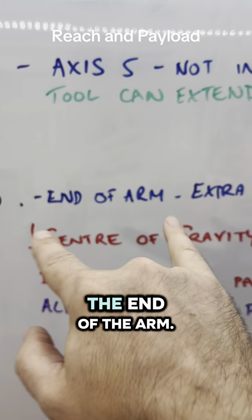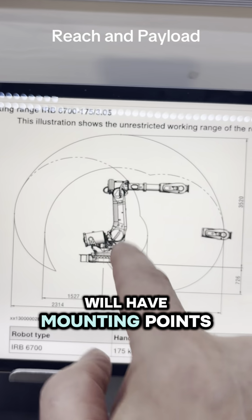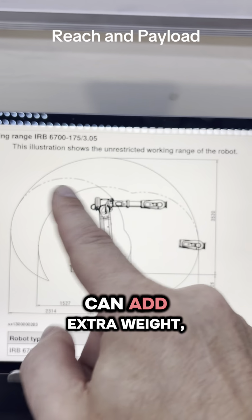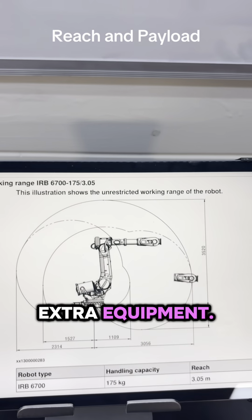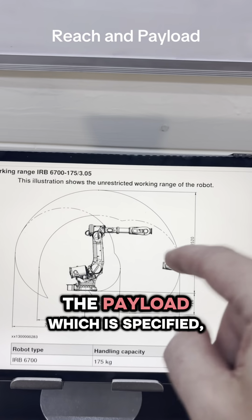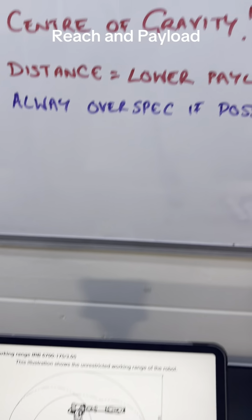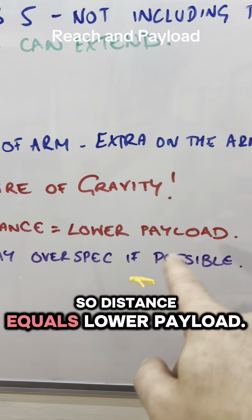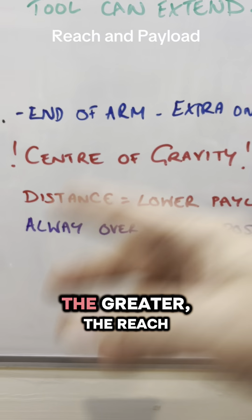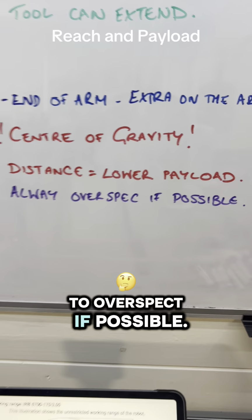But that's just on the end of the arm. There is usually extra on the arm itself. So the robot arm will have mounting points on it where you can add extra weight, so you can carry harnesses and extra equipment. The payload which is specified is always talking about the end of arm. So distance equals lower payload, so the greater the reach, the lower the payload, and you always want to overspec if possible.